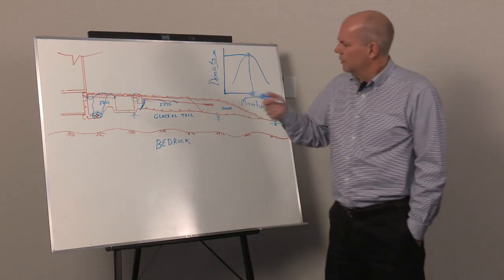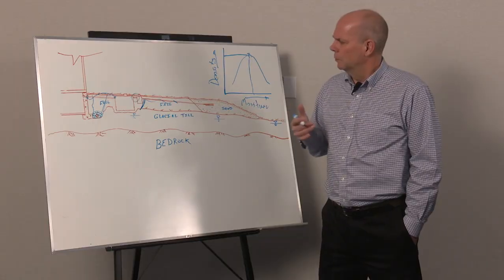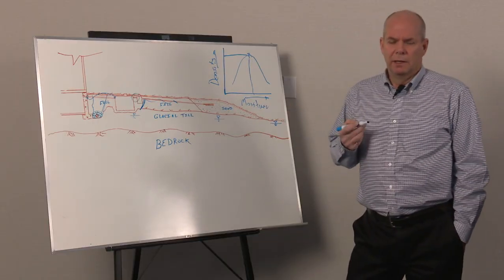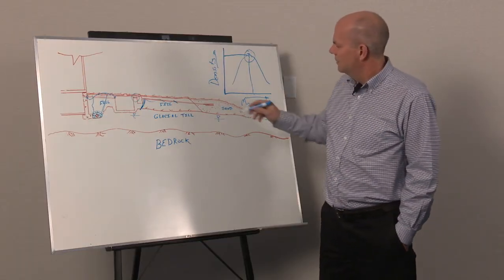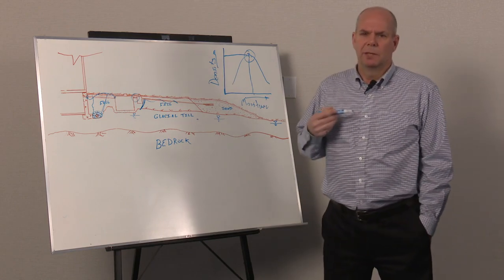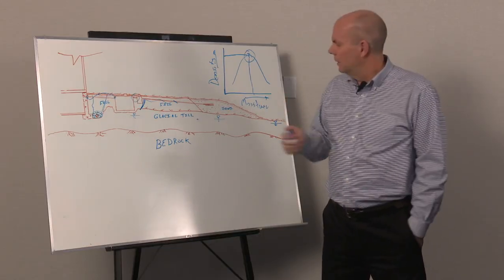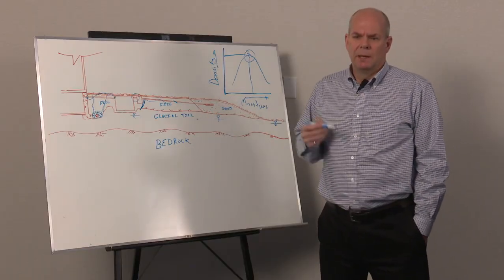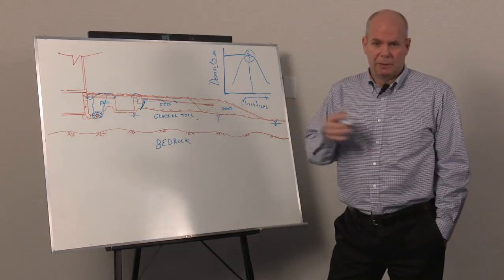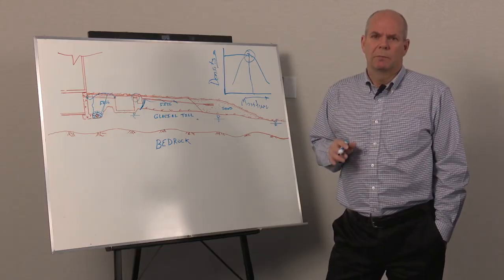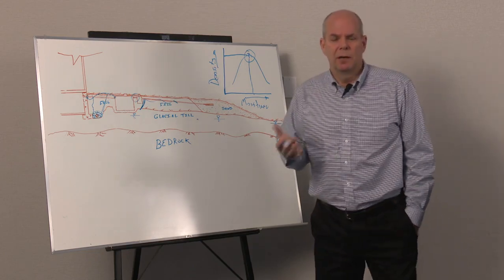So I assume most of the construction and backfilling and stuff here is not done with a bunch of density readings and site supervision with somebody coming out and measuring the actual density of the material being placed. So it's very important as a contractor to make sure that your material is close to its optimum moisture content, and that moisture content tends to be very similar to the moisture content that the material has naturally. So when it's dug out and you're stockpiling it, you want to try and maintain that moisture as close to that natural point as you possibly can. That typically means when you're stockpiling the material, maybe compact the surface of it to keep water from infiltrating very easily and keep the material from forming large lumps that can dry.